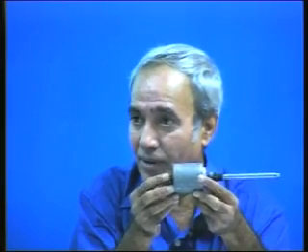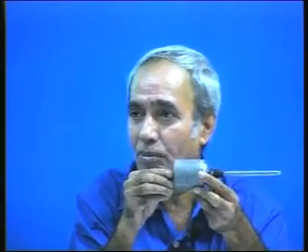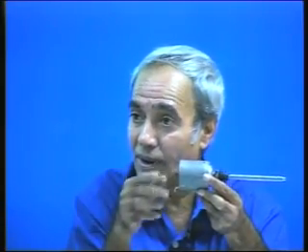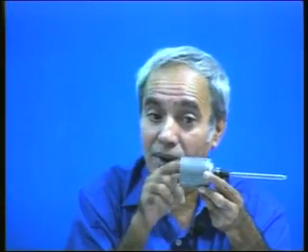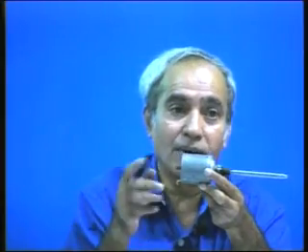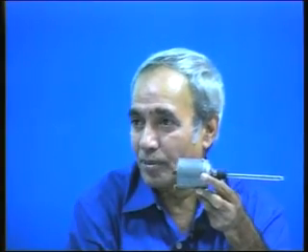You have taken it out of a disk drive. The moment you give it a series of pulses, it will go through 0.9 degrees or 1.8 degrees, depending on how you have configured the electronics. They are typical. Okay. So now you can tell the motor to go through, say, 20 steps, 20 into 1.8, 36 degrees. You send as many pulses and it will go through that and stop.